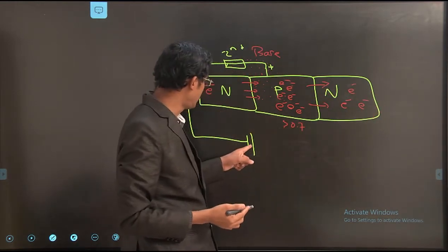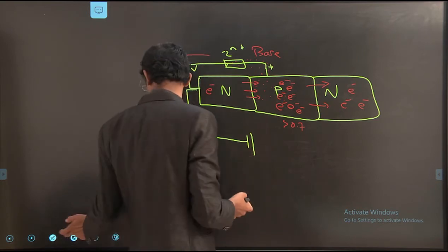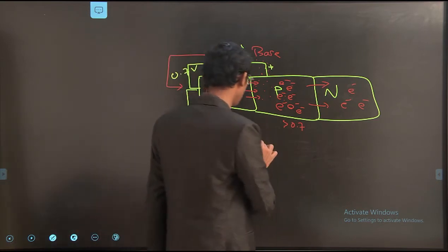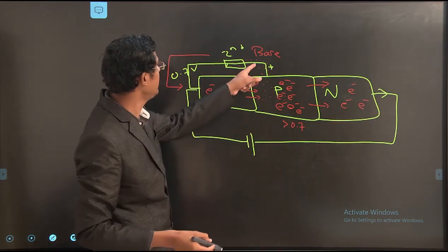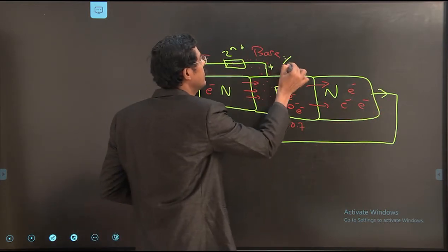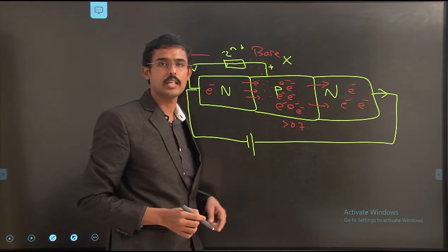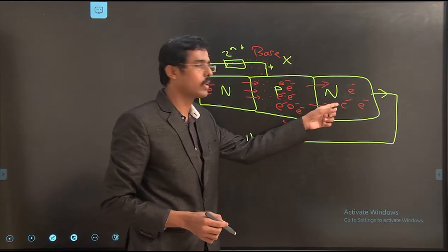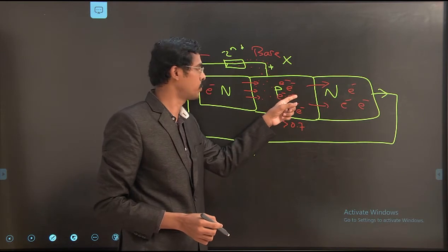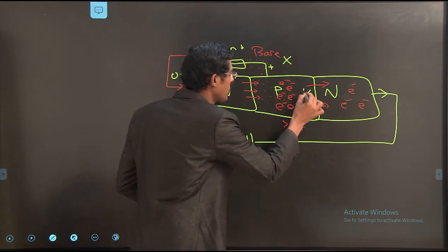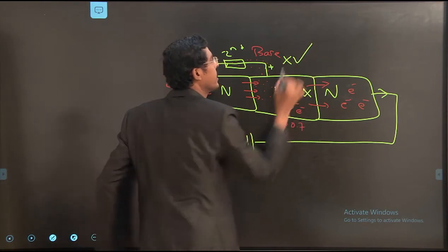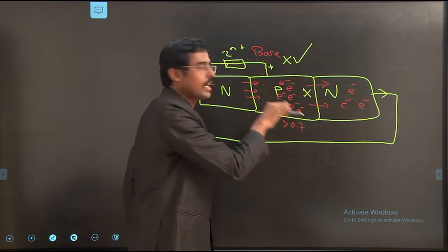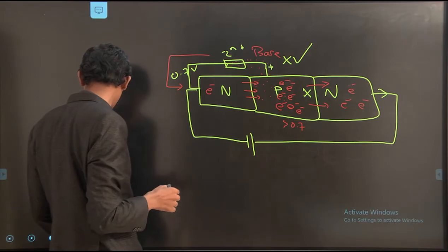Then we have positive here. You see, here we have positive already, so that we are able to connect again and the circuit is closed. Now when the base is disconnected, automatically this circuit of force will not take place. Then automatically the circuit will disconnect. When the base is given again, the 0.7 is generated and it goes again. So that is a simple understanding.